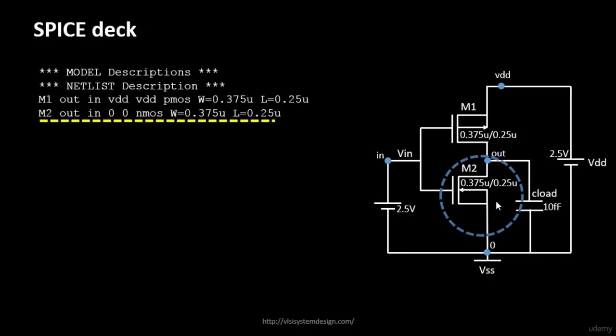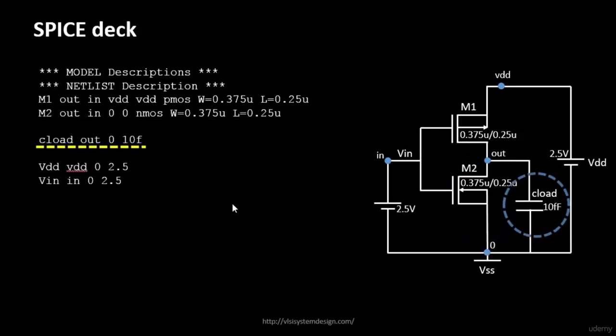Hello everyone. Let's continue our discussion on describing the SPICE deck for the CMOS inverter. So we had described already the PMOS transistor in the last video. So this was the PMOS transistor and this was its respective connectivity information. So it lies between D, G, S, S, so drain, gate, source and substrate. In the last video I had mentioned this as substrate and this as source. So just correcting over here, it's drain, gate, source and substrate.